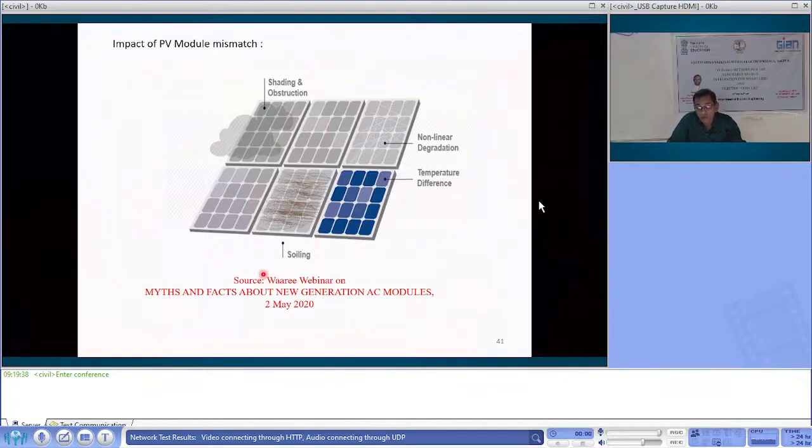Okay, so what happened is that in our electric maintenance section they have put up this solar rooftop plant on the girls hostel, boys hostel, and in summer they experienced that the string inverter, even though they covered it with a canopy, gets hot and after the temperature is high, the capacitor burst. So getting that inverter replaced was a big task for them. So weather conditions are very important, and how we are going to provide cooling in summer, in May and June here on the terrace, because intense heat is there. So these are the factors.